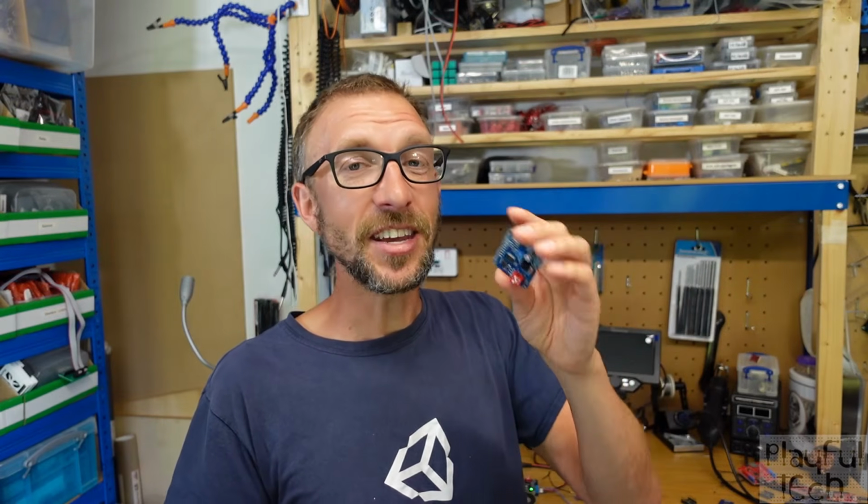Now, I can't really make a tutorial about audio modules without answering the question about how loud they are. So in terms of volume, both the 5W and the 8F boards have the same 5-watt Class D amplifier on them, which can drive 4 ohm impedance speakers up to 5 watts. And that's plenty loud enough for most applications. It's also perfectly clear enough to hear speech.